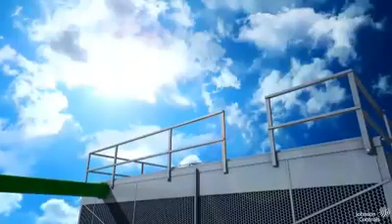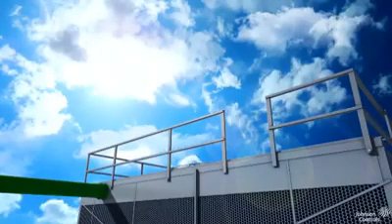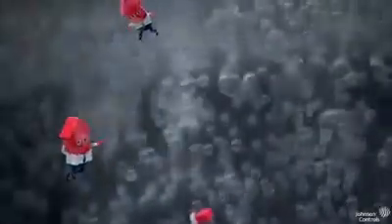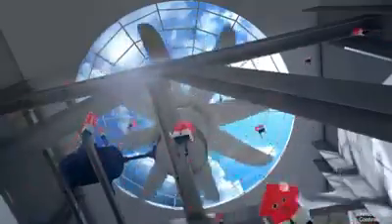Condenser water is piped into the top of a device called a cooling tower. Cooling towers are designed to reject heat to the atmosphere through evaporative cooling. As Mr. BTU and cohorts are sprayed into the open air inside a cooling tower, airflow around the water droplets in which he is hanging out have less heat energy. By now, you know the drill. Some of the heat energy his gang carries changes the state of the condenser water from a liquid to a gas. Some of it directly transfers to the air.